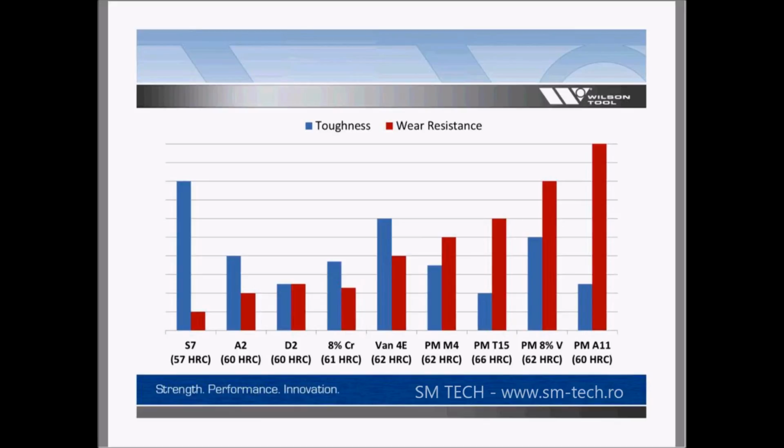So actually going to a 3V, where you're giving up a lot of that wear resistance, which is more in that Vanadis 4 Extra range, you'd see tremendous gains in toughness, and the wear resistance is still okay. But then combine that with the coatings. Never forget the other options you have available besides tool steels. Coatings are always a big play in that. And surface finish, changing the direction of the grind of the punch, adding a polish to it in a galling issue, that might help out in that process.